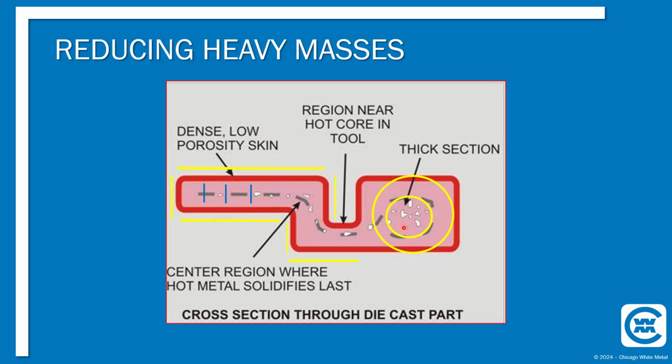So this is one reason why, if you can have some very common wall thickness throughout the part, you minimize the amount of this type of area that has a cooling factor or timing different than another area of the part. This also shows why on the previous screen I mentioned how much of a machining stock to take into account.